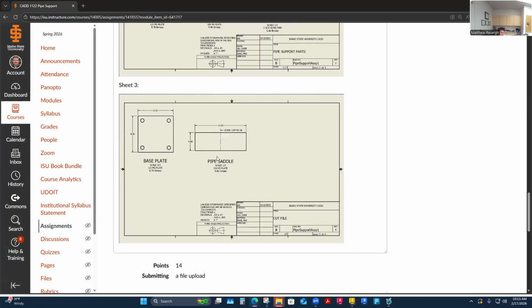Really, I just want the bending and rolling center lines to show up. Other than that, it's real simple. I can make a DXF file of just this sheet to send to my nester. Generally, we would print our cut file sheets for all of our general fabricators, and then we would also make a separate DXF, PDF, or drawing. Usually it was a DXF or DWG file for CAD that the nesters would grab.